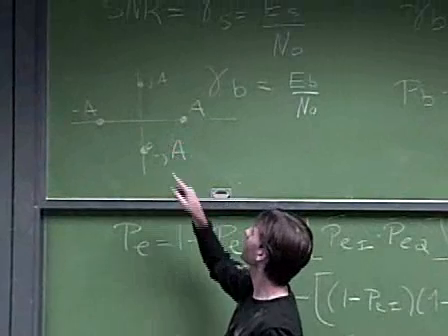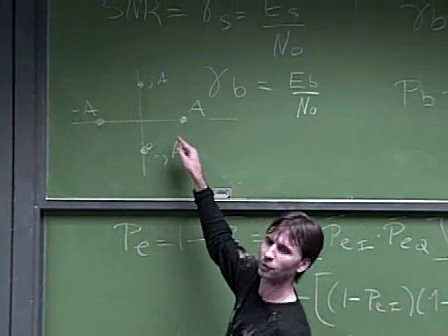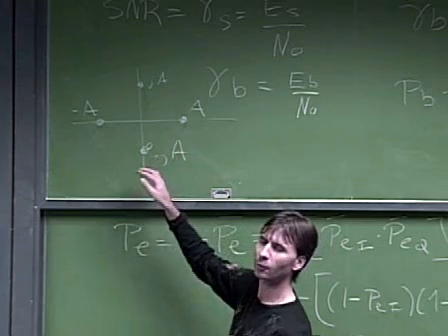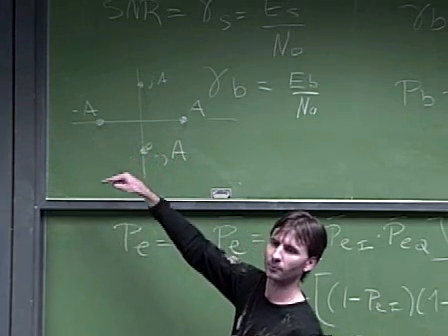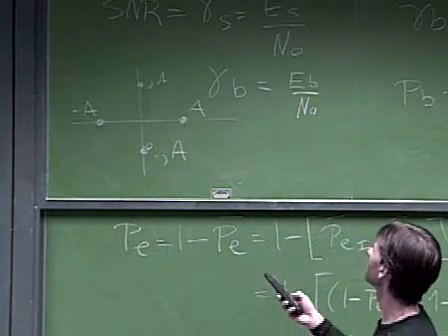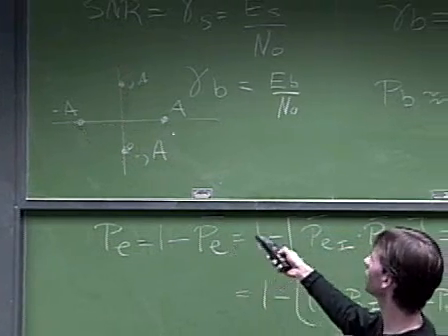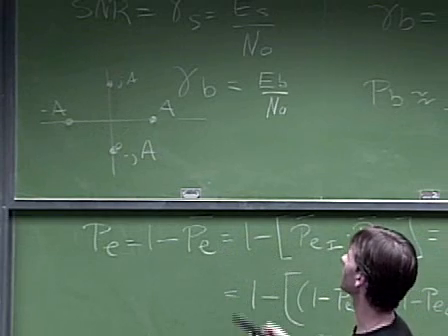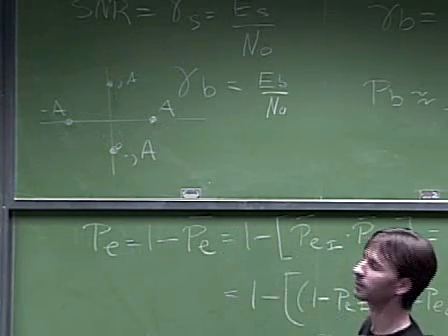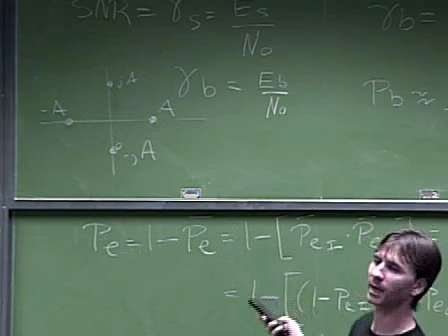But the final destination of the error could actually go to the other BPSK, is what you're saying. So what you're saying is correct, but it doesn't challenge the fact that the chances that each of the two bits is in error are the same because the noise has the same properties in both directions, right? So this is true because the noise is Gaussian, right?